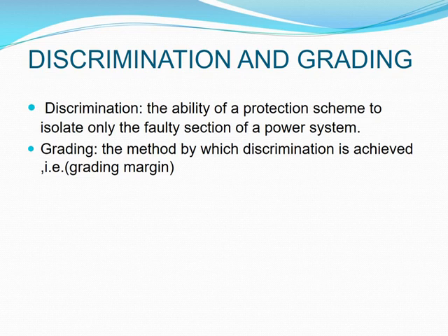So in a scenario where you had an interconnected system, which you would have learned in the previous module on electrical engineering 3, and you had another cable that was feeding that same motor, the one that has got a fault, if you isolate it, then you could still have some power going into that motor, which means that your load can still be operational.